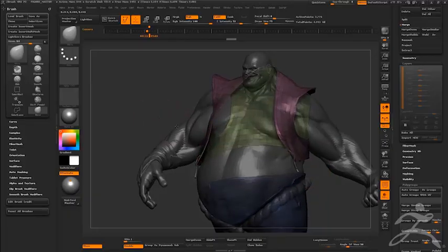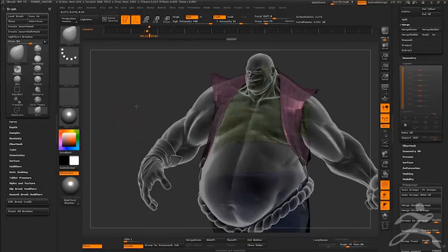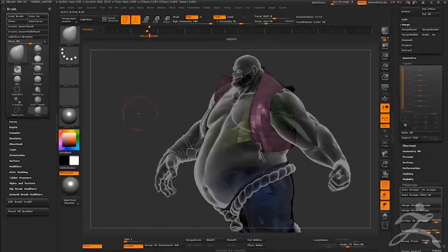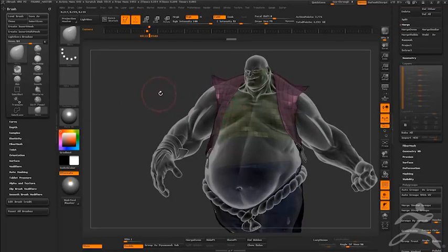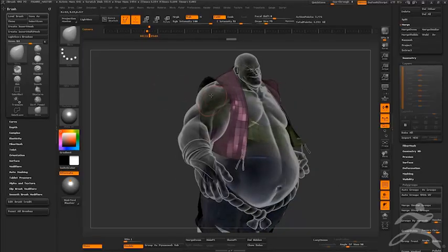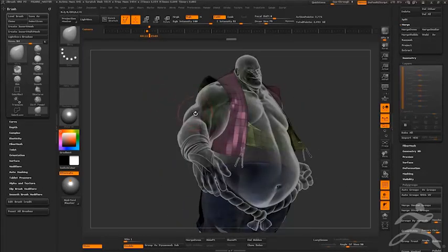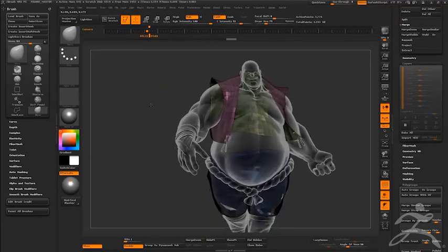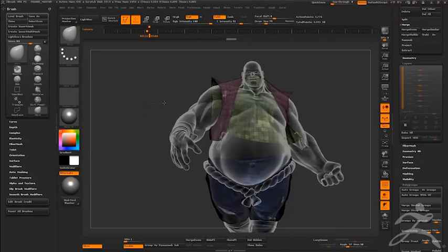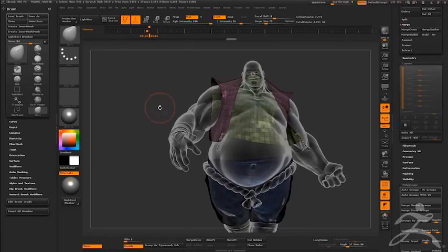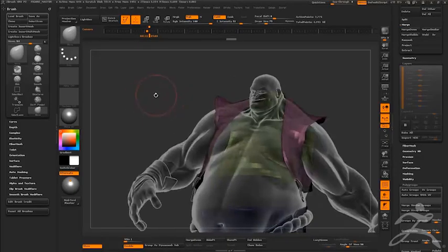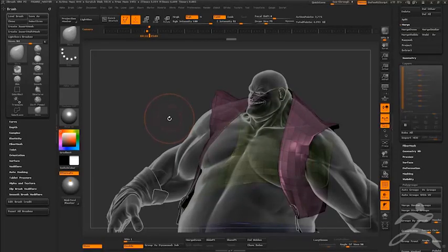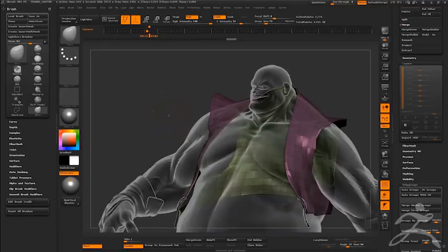And putting it in transparent mode and even ghost mode, you can kind of see that this inner surface is not biting through enough the torso of the figure here. The objective is to just boolean everything together into one object. Some printers recognize multiple meshes as one object. Some of them don't. I like to err on the side of caution, and I want to create a model that has the fewest parts possible, that makes for more accurate printing with fewer mishaps and misprints and things of that nature.